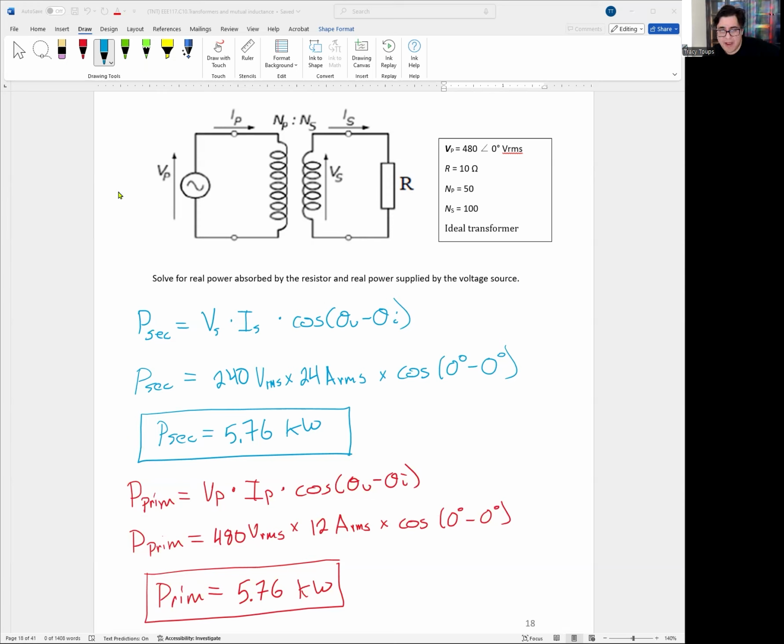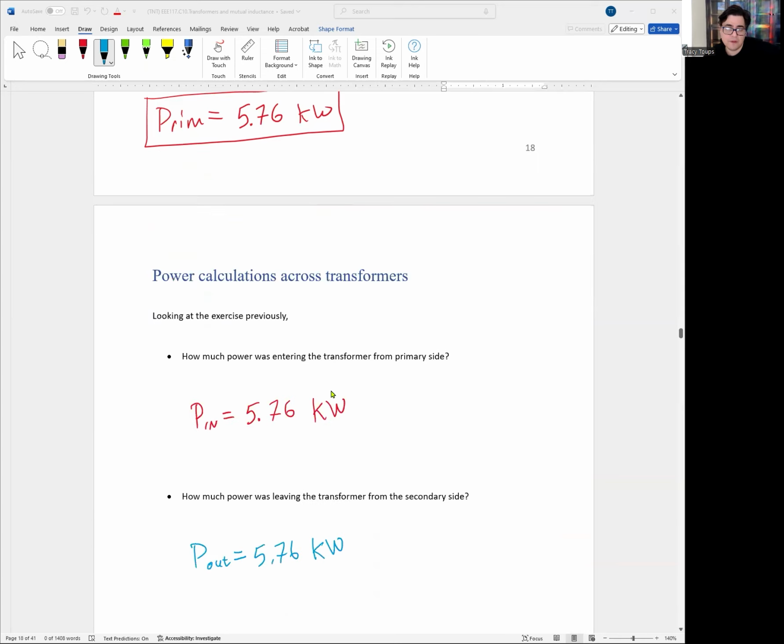Is that the power going in through a transformer must equal the power going out. Because the transformer itself does not absorb a lot of power. It's not a load, it's not a source. So it's just a pass-through device. Okay. So to make the powers equal, the voltage goes up a certain ratio, the current has to go down a certain ratio to make sure the power is equal on both sides. So that's why there's an inverse relationship between the change of voltage and current in a transformer. It's just physics at the end of the day. Okay.